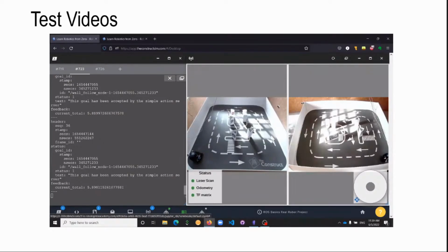It has to satisfy two conditions to judge whether the first lap is finished. The first one is the robot has to move more than 7 meters. And then the second condition is the latest point that this robot passed by has its minimum distance to older points.